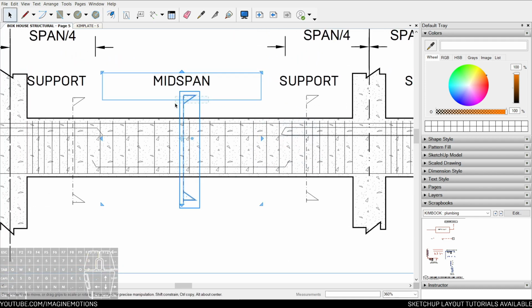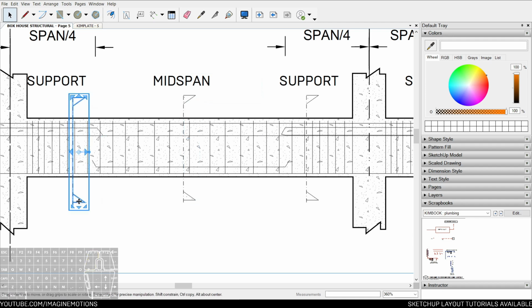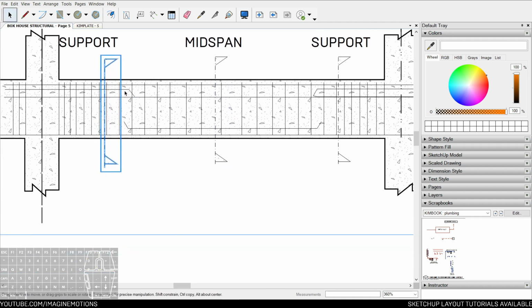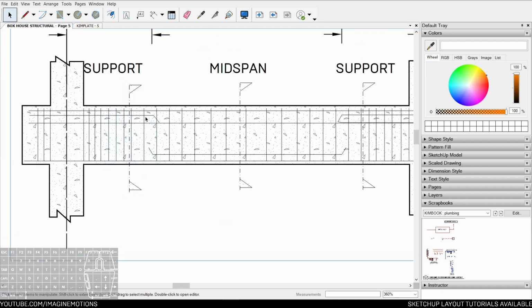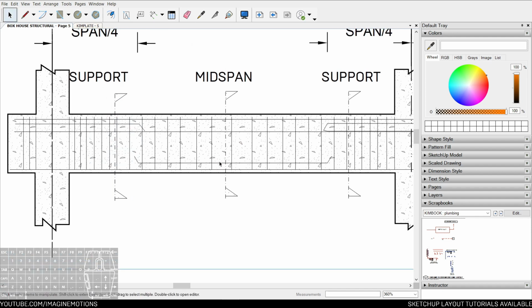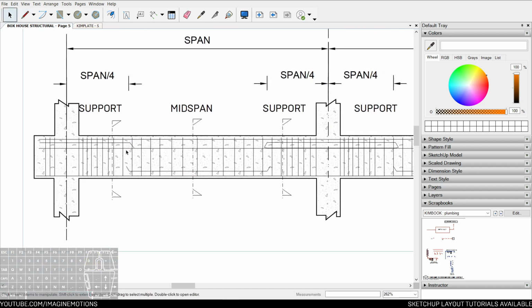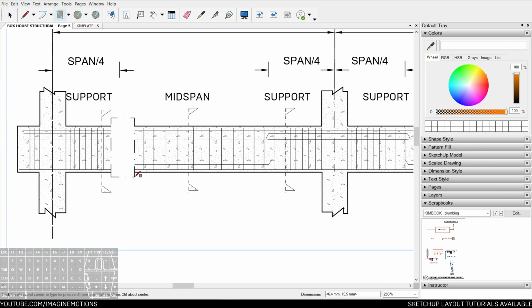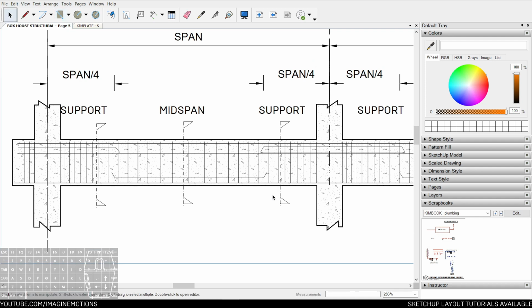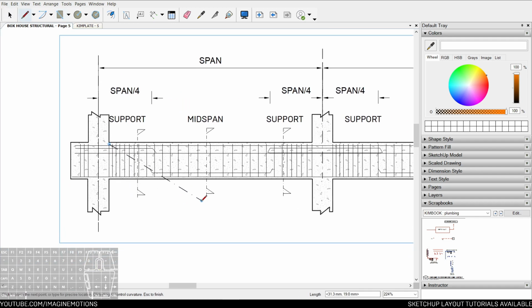And then these are section symbols to say please look at the section detail for the arrangement of these rebars. Is it 16 millimeter or what? Okay. So since our load goes down here, our reaction force against gravity and weight goes upwards. These are important because the span of these will determine also how strong the support is. We do not want our beam to bend downwards or to buckle.